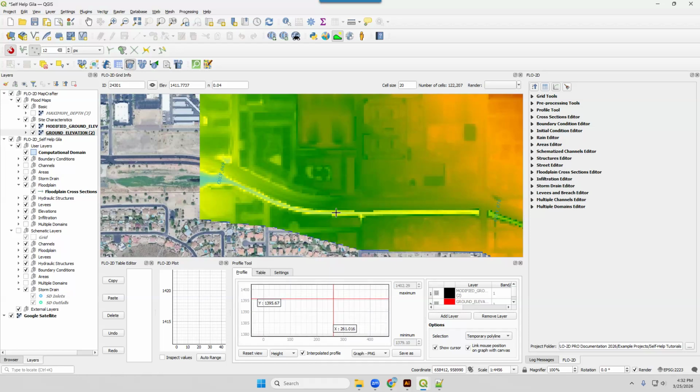Okay. And so that's the difference. Oh, and there are a couple more differences. The modified ground elevation also is modified at the rim elevation of inlets if the rim elevation of your inlet does not match the grid elevation of the grid element that it's connected to. At runtime, the Flow2D engine will reset the elevation to the rim elevation of that inlet, of that node, okay?